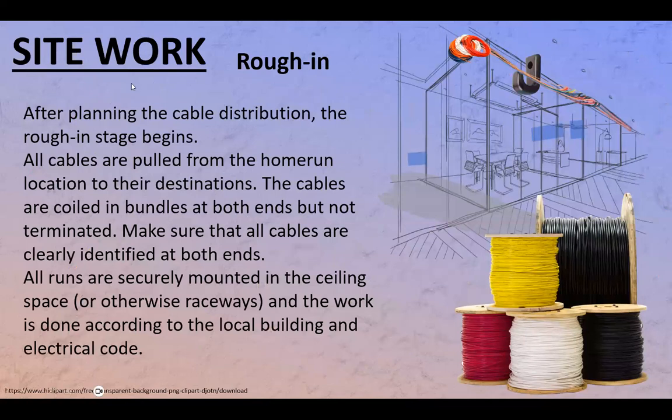All right, site work. Remember, I was going to come back to it. We are dividing this site work into, let's say, infrastructure type of installation, cabling, basically. After planning the cable distribution, the rough-in stage begins. All cables are pulled from the home run location to their destinations.